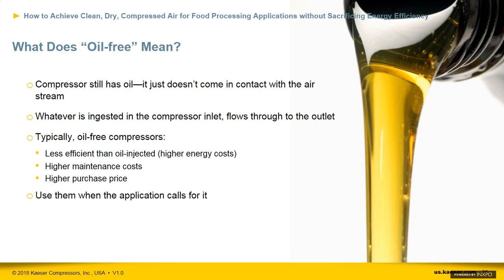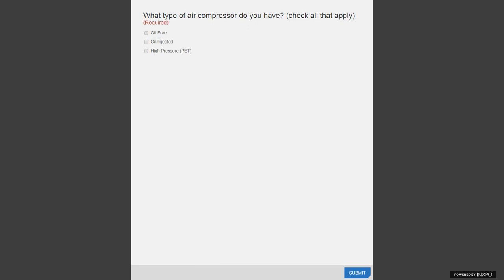Also consider that oil-free compressors are usually less efficient than oil-injected units. They also cost more upfront and they may have higher maintenance cost. But they could also be a wash or less cost based on the different designs, and also depends on the size of the units. That's not to say that they're a bad choice. They should just be properly applied. Examples of some possible appropriate applications would be direct food contact and in many pharmaceutical, electronics, and chemical processes.